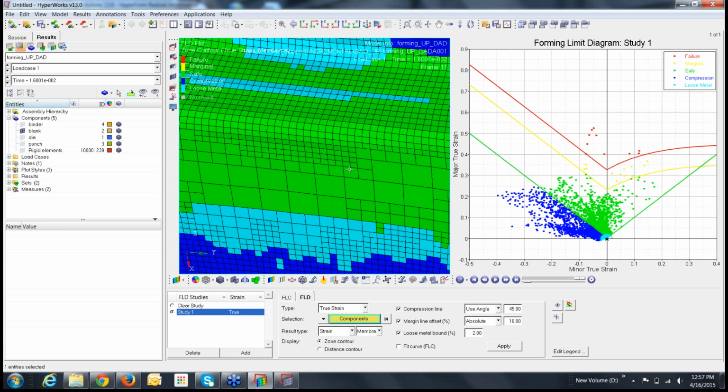Then further this 4 got divided into 4. So this is your 2 levels of adaptivity. This is your first level of adaptivity. This is your second level of adaptivity. Until it captures that feature, it keeps on adapting or dividing itself. The regions where it's not needed to adapt, it remains as it is. This is called adaptivity.